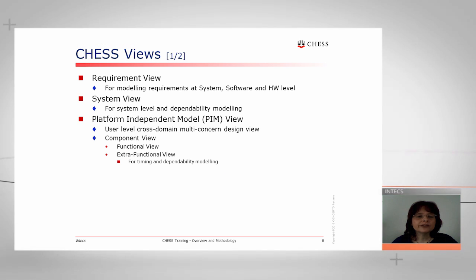Now I'll give you a brief summary of the CHESS views used to address different concerns. The requirement view is used for modeling requirements at the system, software, or hardware level. The system view is used for system level and dependability modeling. The platform-independent model view is where the user can model components, can define their functional properties to specify the component's